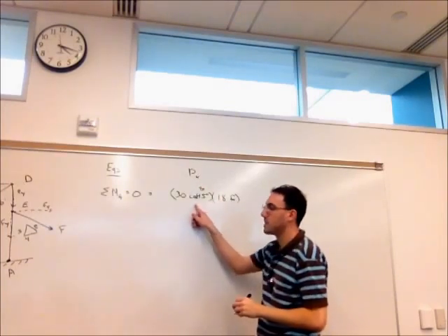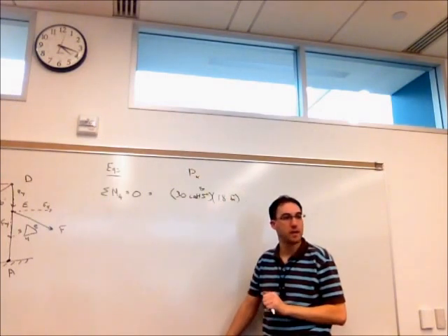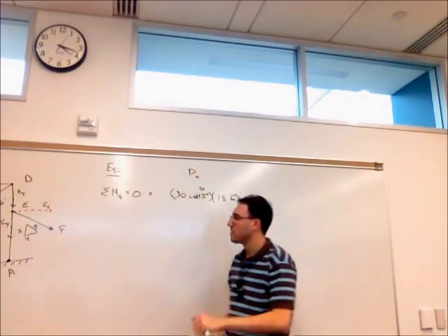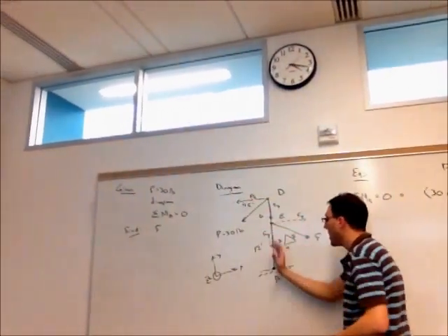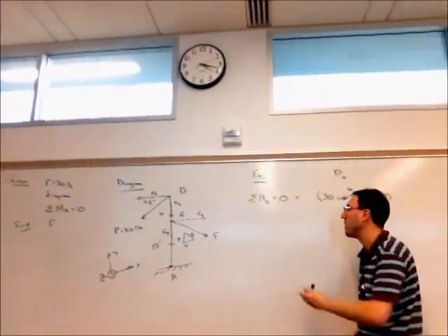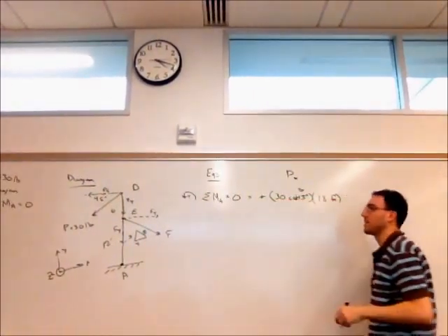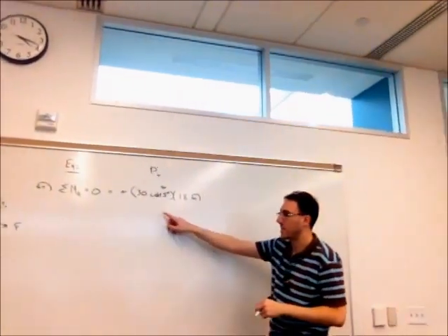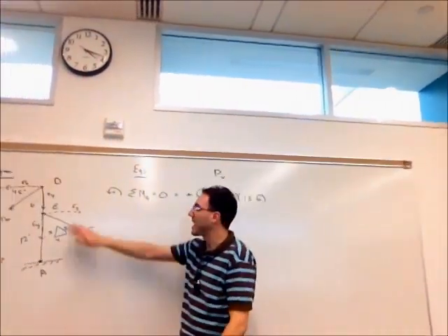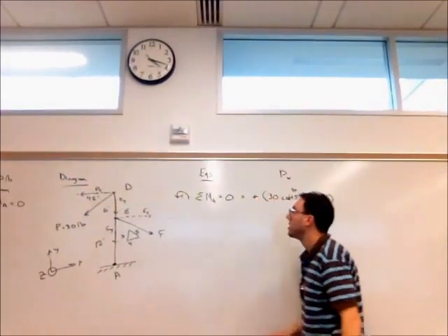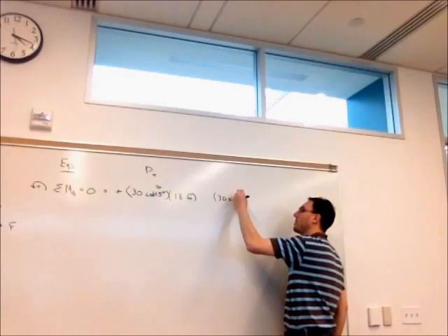And then is this Px force a positive or negative moment around A? Right, it's positive, so again, holding at A, pushing in this direction, it's creating a counterclockwise moment around A. I will include positive there just so we remember that we actually did check and it was positive. We broke this into that second force, Py. So Py is going to have a value of 30 sine 45.